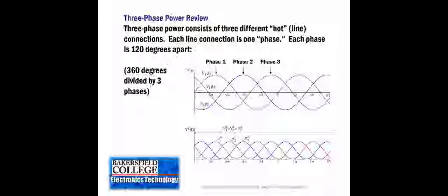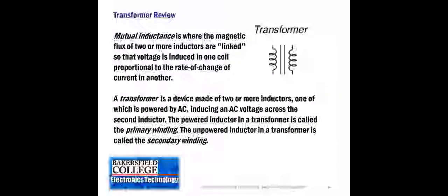So actually 480 volts divides across the coils at 277 volts. So across the coils, you're actually not taking 480 volts. You're actually taking 277 volts. But if we take 277 and multiply it by 65%, now you remember that a transformer uses the concept of mutual inductance, so that at the primary we put current into the total turns of wire in that coil, and that creates a magnetic field that cuts across the secondary coil. So that'll then be 180 volts. So when it's operating on the reduced voltage or low voltage connection, between points C and E, that's 65% of the coils, then you will actually have a voltage in that 180 volts.